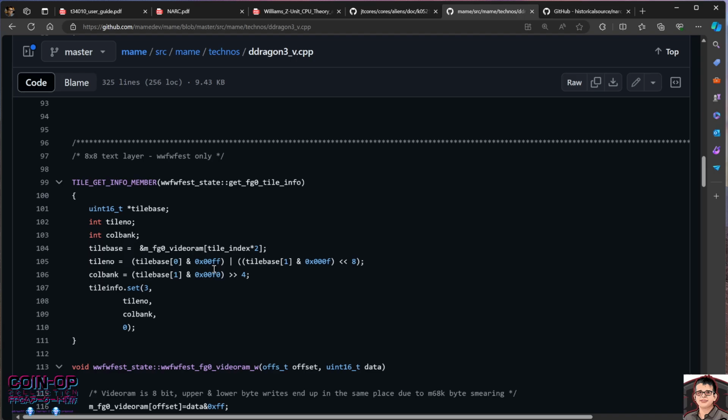Not very many, because you can imagine that there's a lot of memory required for that, right? But the point I want to get across is that if you were copying MAME directly, that wouldn't work, right? Because the graphics are just drawn differently. That's not how the original board behaved. And actually, if you do it this way, you're potentially going to face memory constraints. You may not even have enough memory to do it, depending on the color format, how many bits per color you have to work with, and what the pixel clock is, right? You may not even have enough bandwidth to do it.